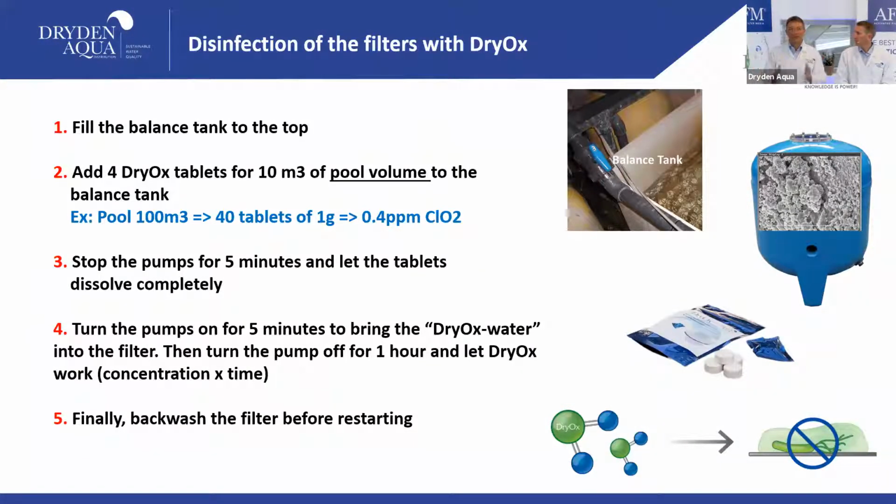So the CT factor. I would recommend you wait for 1 hour, and then you make a backwash. And then you make a proper backwash to get everything out. And then you restart your filtration. Can I combine this a little bit with chlorine? Yes, that's actually a very good idea too.